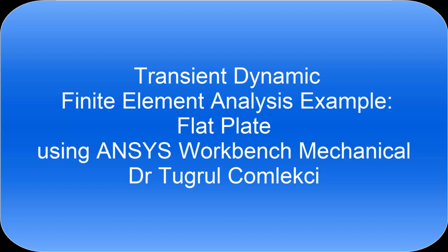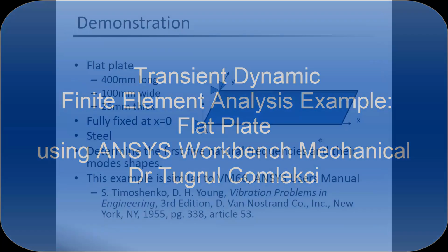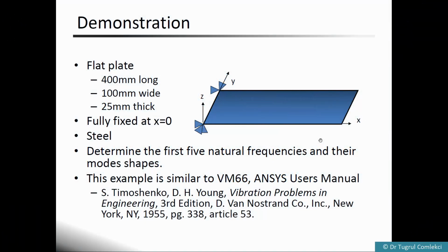In this demonstration, I'll look at a modal analysis followed by a transient dynamic analysis of a flat plate, which is 400 millimeters long by 100 millimeters wide and 25 millimeters thick. It is fully fixed at the x equals 0 edge, and it's made of steel, and we are going to look at finding its first few natural frequencies and their mode shapes.